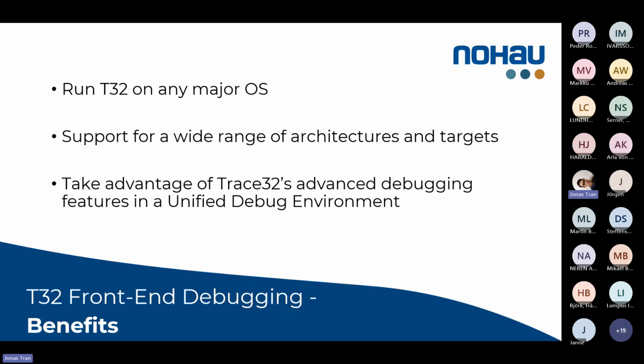And TRACE32 also supports a lot of APIs, so it can connect to almost any emulator or simulator or virtual platform environment. And by using TRACE32, you can take advantage of its advanced debugging features, which includes visualization of the data, for example, graphs and charts, to help you get a more comprehensive understanding of how your system behaves.